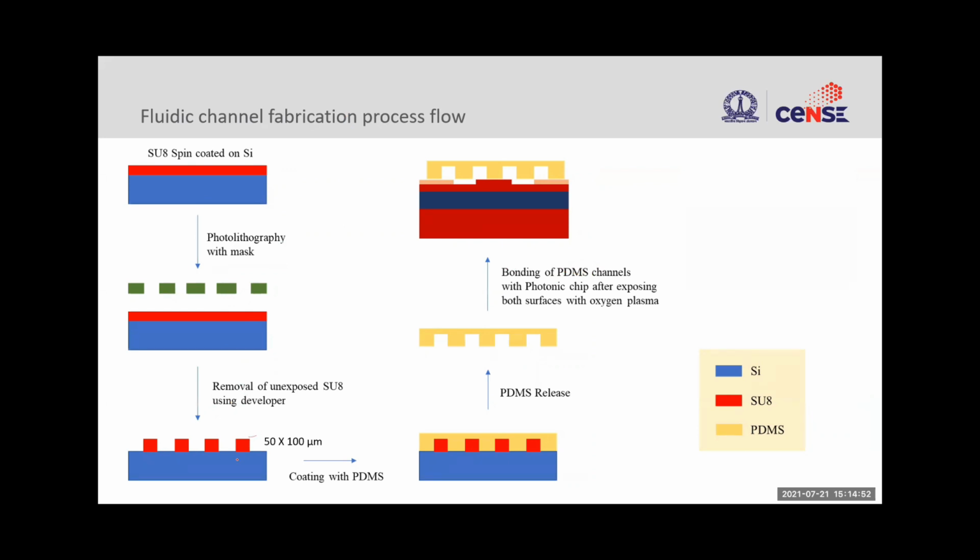So you have rectangular channels of 50 by 100 micron. They are 50 micron in height. Sorry, the thickness is 50 micron, not 100 micron, and they are 100 micron wide. One can make it even smaller. This is just the alignment accuracy that one can place these molds, but this is reasonably large for this application. After making this SU8 template, we pour PDMS on top and cure it.